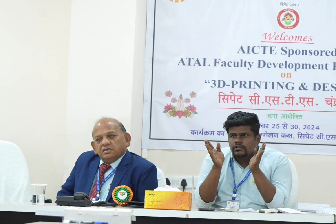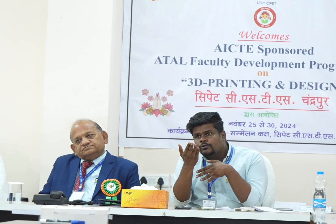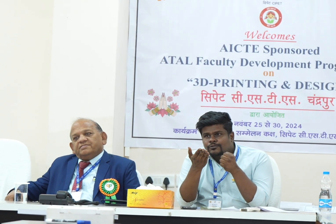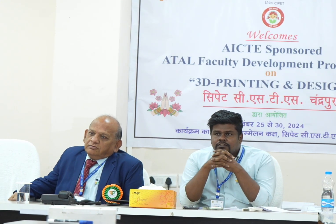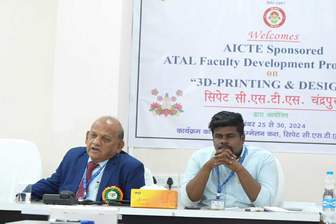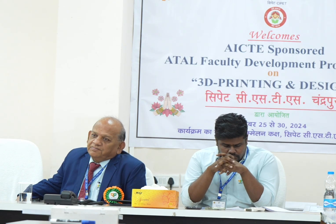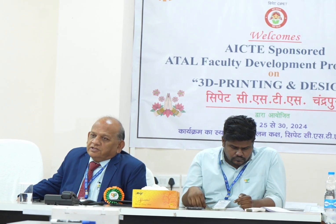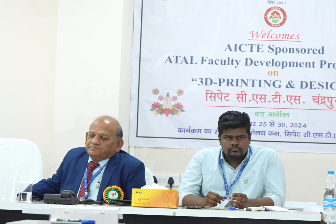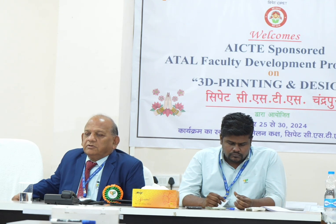In the overall sense also, if it is a conventional method like casting, what are the defects coming in the quality check? Cracks, porosity, rat tail, all these defects are there in everything. In casting also, blow hole, maybe a chance, due to the presence of air. Everywhere there is a phase change, liquid to solid during solidification, there is a chance of reaction with the atmosphere or some other particle formation. There will be contraction and expansion. The chances are there.